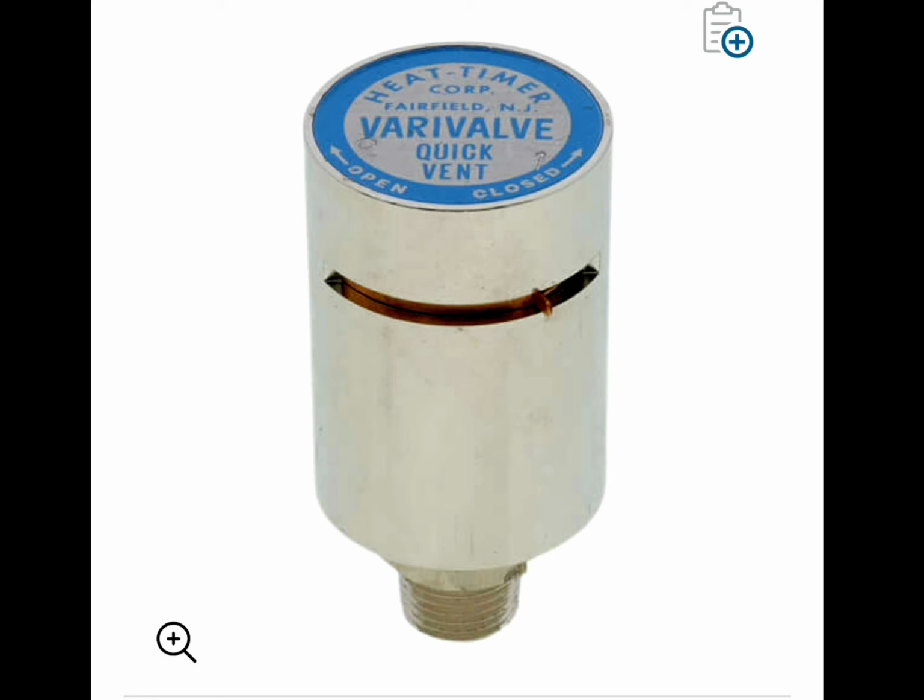Now, if the air vent's on the radiator, it should sustain the same temperature as the radiator. Why? Because it's a thinner metal on the radiator, but that's not the same case with this. And I've had situations where I put them on a steel convector, and you have these problems. The radiator starts cooling down, and it takes too long before this thing finally realizes the temperature's cooled down. It's time to open back up and get the radiator hot again.